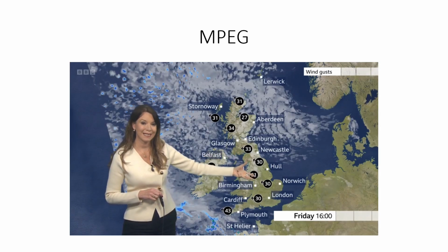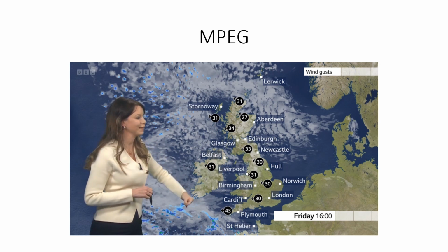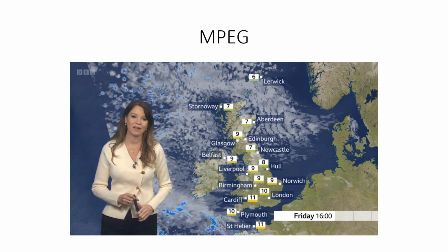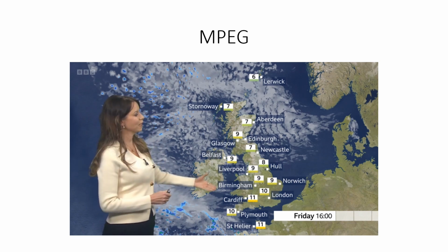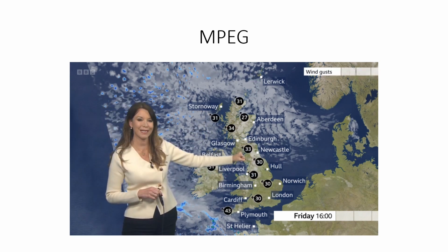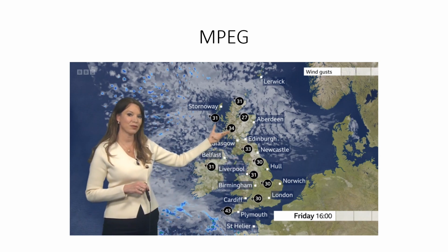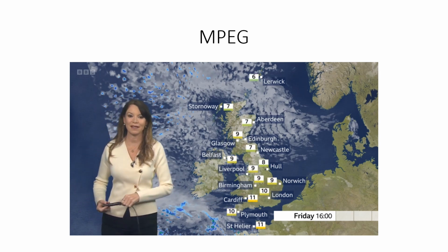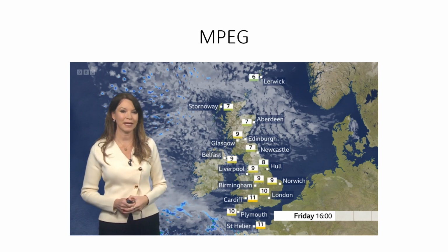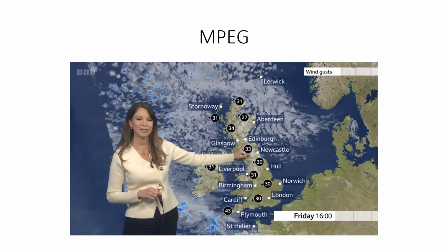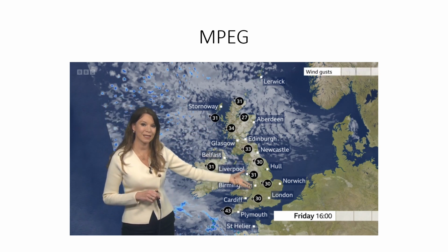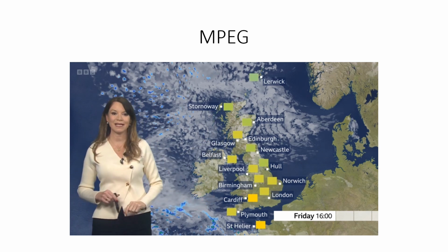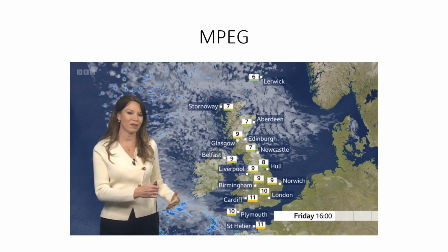Video compression makes use of two features of video. Since the video is a succession of still images, it is possible to compress each frame in the same way that still images are compressed. This is known as spatial intra-frame compression. The second feature is that in general, successive images of a video vary very little unless there's a lot of movement in the video, making it possible to dispense with the unchanging or redundant part and send only the difference. This type of compression is known as time-related interframe compression, or temporal discrete cosine transform compression, DCT.